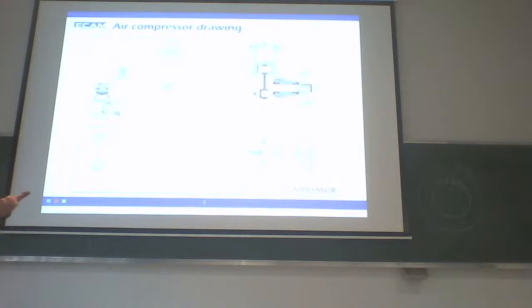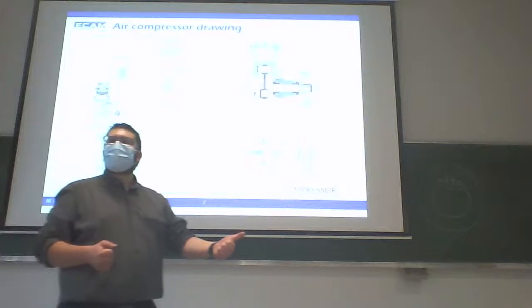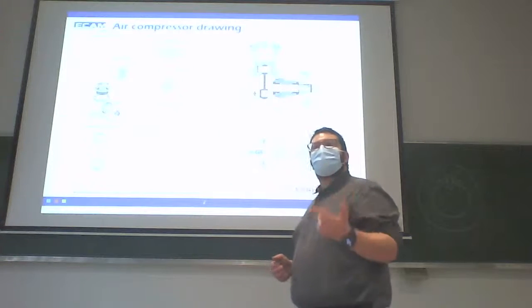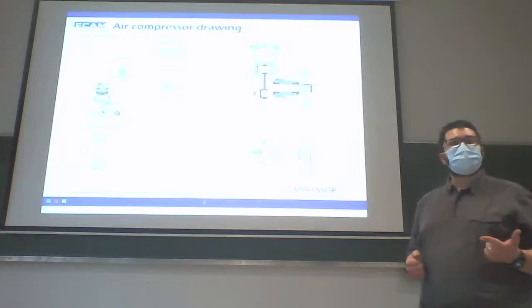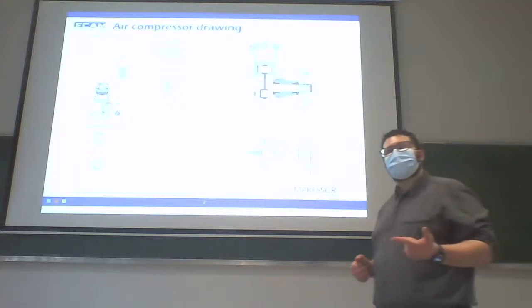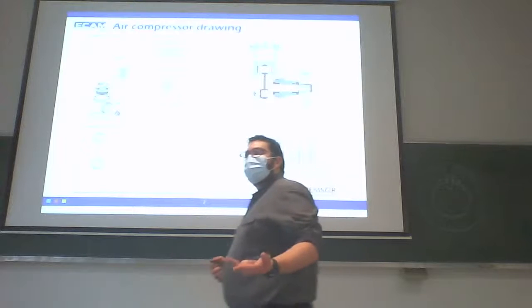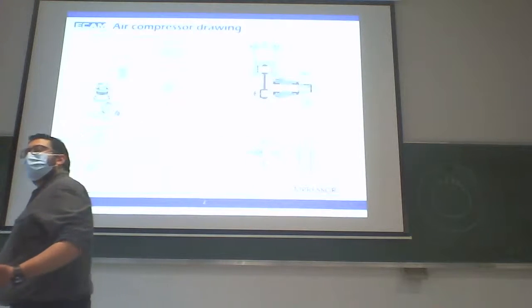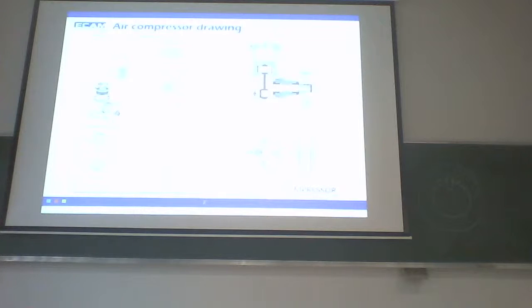First step, identify the group of parts. Second step, identify the joint between the different groups of parts. And last step, draw the kinematic diagram. I leave you to read this document. I will print it and someone will give it to you.